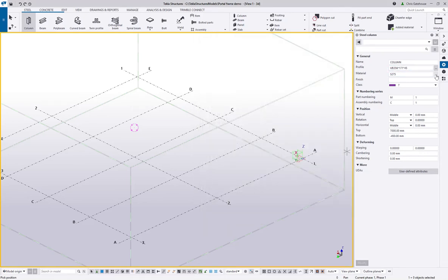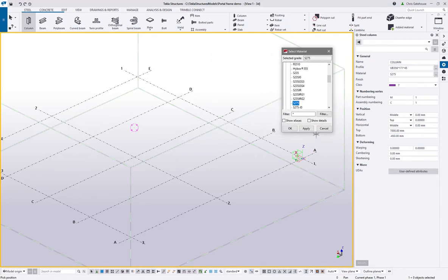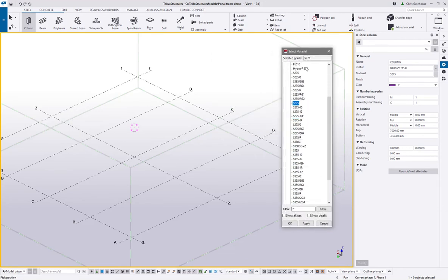So we pick that there, and we've got the same or similar library for grades. So we bring up that library, and you can see here under steel, we've got all of the steel sections. We've got the legacy ones here, the 43 and 50 for chaps as old as me who'll remember those. We've got stainless steel, we've got cold formed hollow sections, we've got some ferrous, and then we've got the mild steel grades along here. Further down, we've got concrete, timber, and miscellaneous.